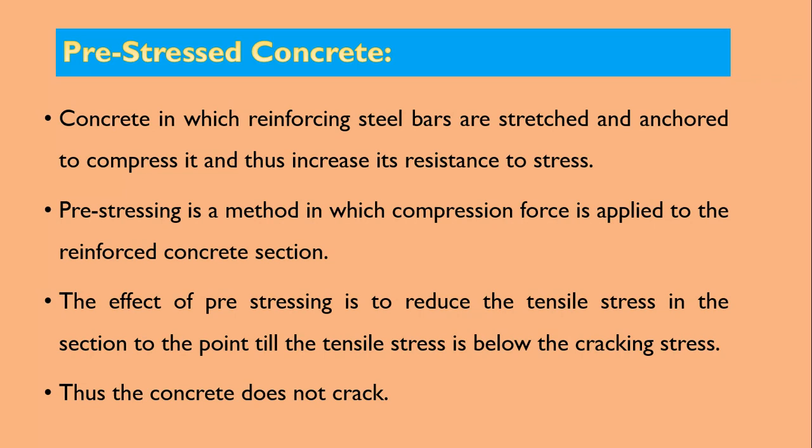So prestressing is a method in which compression force is applied to the reinforced concrete section. The effect of prestressing is to reduce the tensile stress in the section to the point till the tensile stress is below the cracking stress, and in turn you can say to increase the compressive strength. Thus the concrete does not crack.